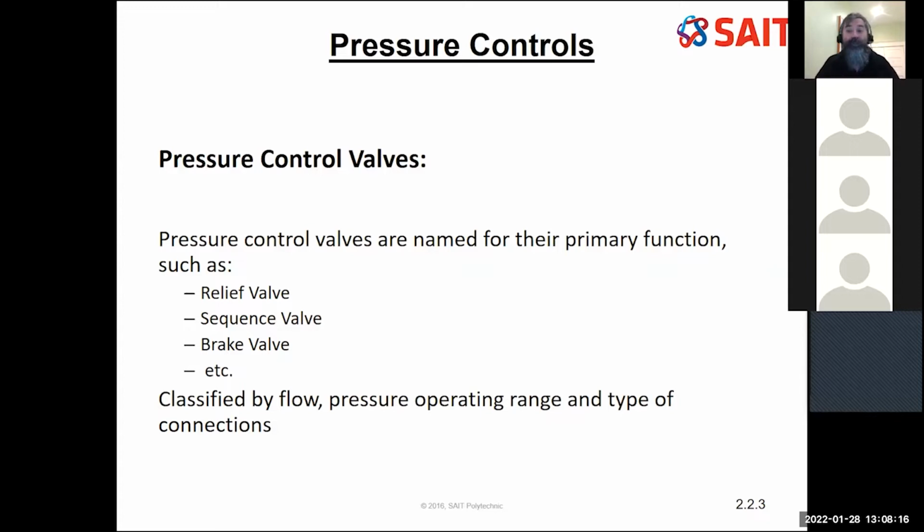What's the maximum pressure it can handle? What's the flow rate that can move through the valve? What's the operating pressure that we're going to operate at? Do I have a screw-on fitting, or is it a different type of fitting that we have on the valve? So there's a large list of things. Even when I know which sort of valve I want to use, I have to start thinking, what sort of valve is it? Is it a cartridge valve? Is it a stack valve? There's a large number of things we talk about when we start classifying our valves.